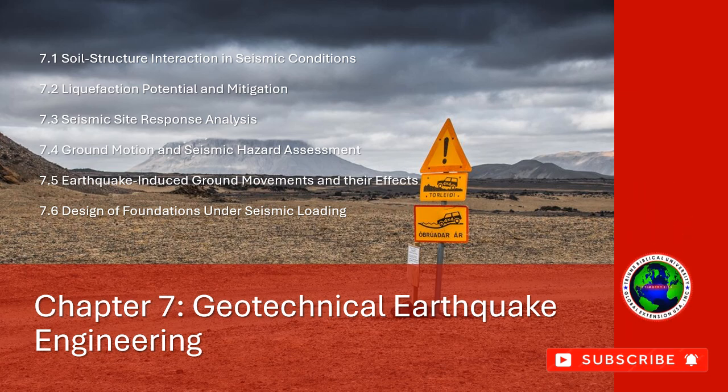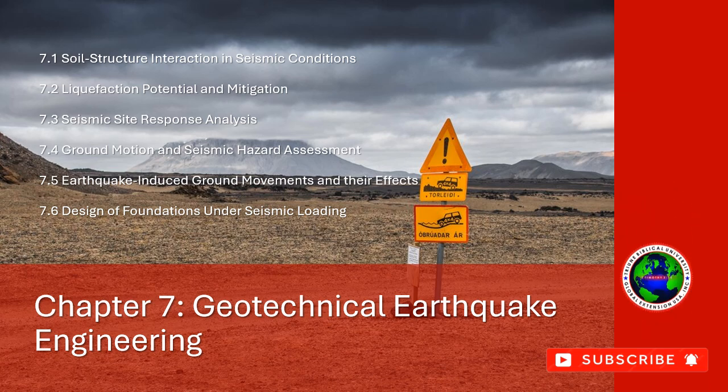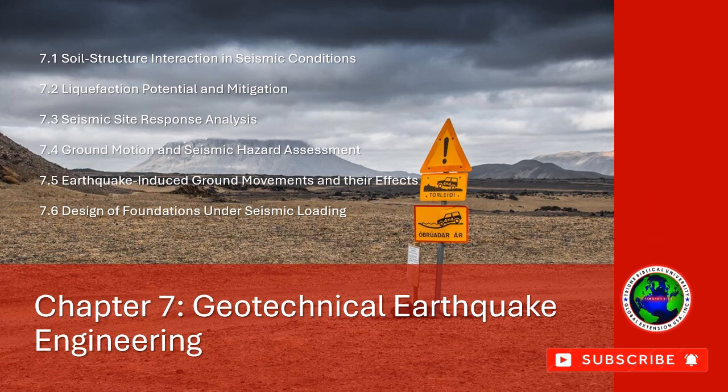4. Pore pressure and shear wave velocity measurements. Measuring changes in pore water pressure during cyclic loading can help assess liquefaction potential. Shear wave velocity measurements obtained through methods such as seismic refraction or downhole testing can provide information on soil stiffness and the likelihood of liquefaction.